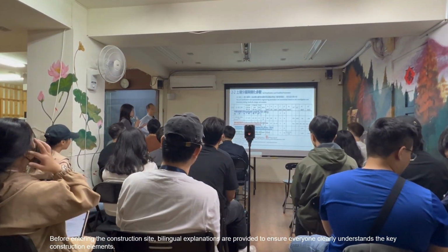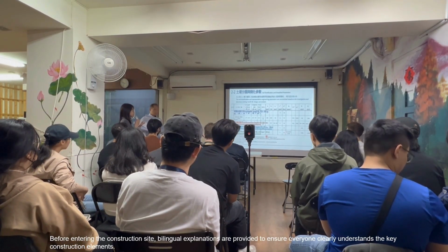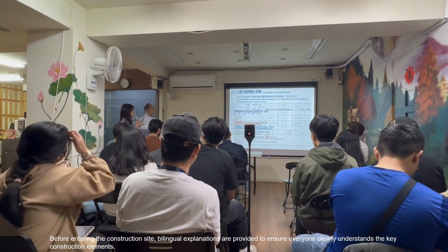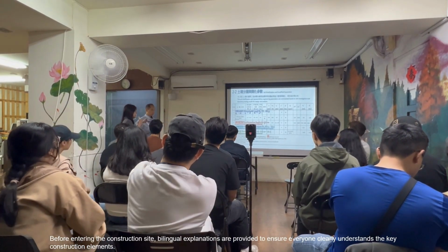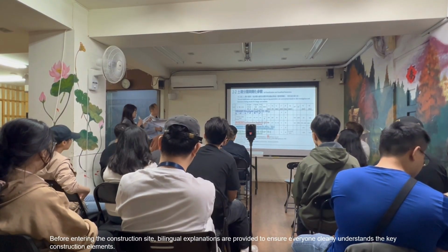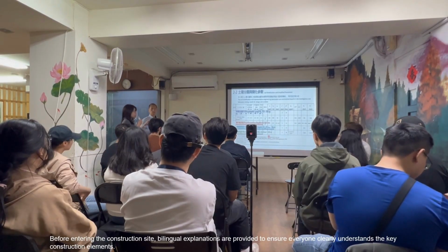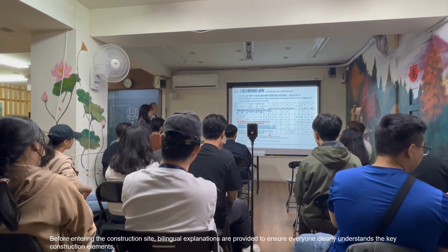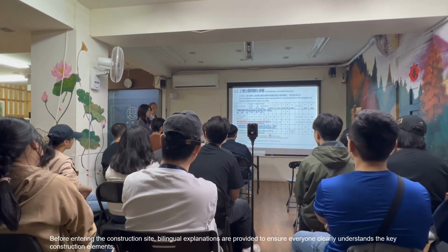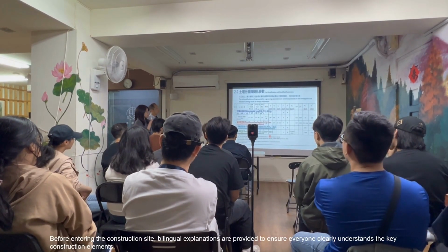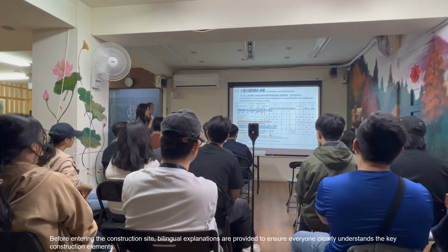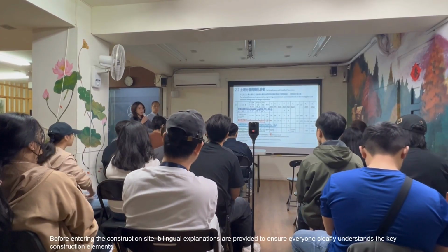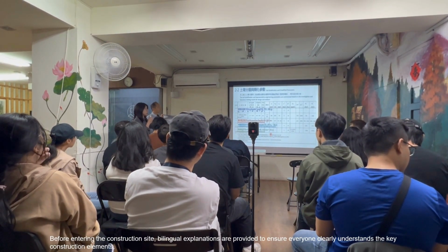So this slide is, as I mentioned, very important. We have to try to know what we have for our soil profile and how we do site characterization to well prepare this simplified soil stratification for design. You can see we have SPT N value, and also water content and some strength parameters like friction angle and cohesion. And also we have the modulus, and these are for the foundation conditions. Some parameters just describe the soil properties.